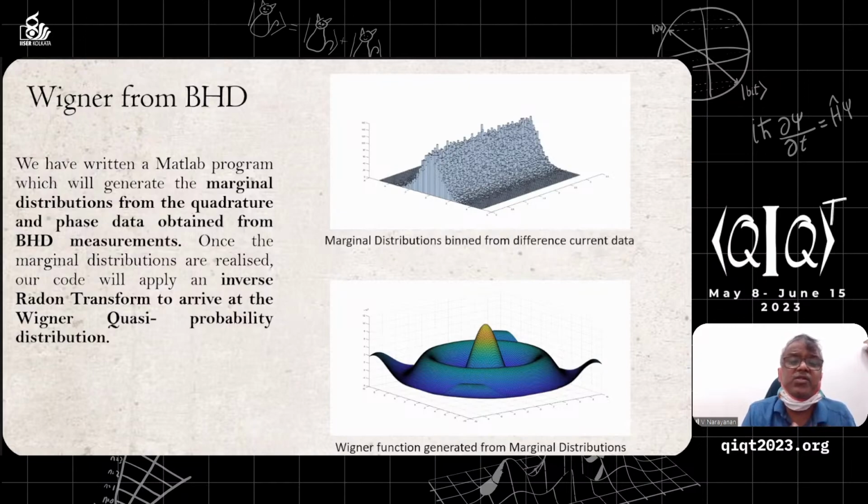We have calibrated this. The challenging thing is you have to fill each individual photodiode. You should not miss the photons. So the coupling of the light into the active area here is very, very challenging. And I would like to point out the detectors used are not at all very expensive. Say, for example, a single photon detector is something like 2.5 to 3 lakhs.